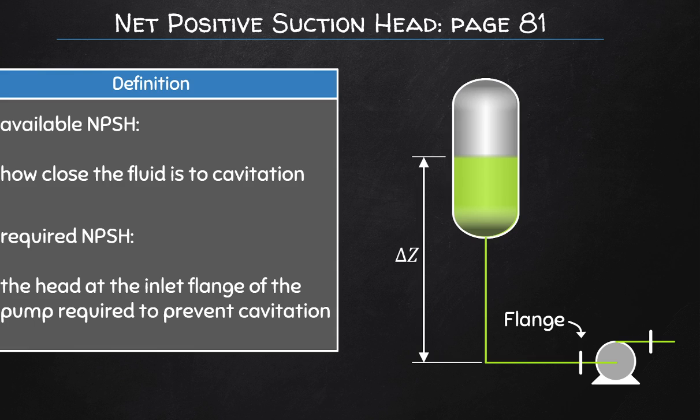Okay, and this obviously will affect how the fluid mover can be specified based on the upstream pressure that is obtained. Now firstly, the system itself contains a certain amount of available net positive suction head, and this amount needs to be matched to the requirements specified by the fluid mover itself.